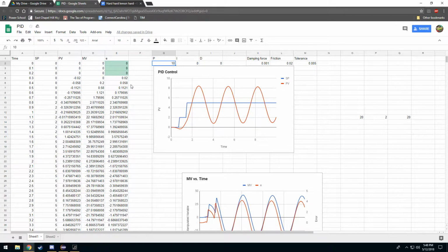And so this kind of introduces the idea of PID, or PID control, and that's exactly what it's going to do. So let's say you graph, kind of like this graph, your sensor value on the y-axis. This is what your sensor is telling you the motor is outputting, or wherever the elevator is, for example. And this is your time. This blue line represents where you want to be. So right here is our endpoint. Let's say this is 5 feet. You want it to be at 5 feet. And red represents where the motor is actually going.